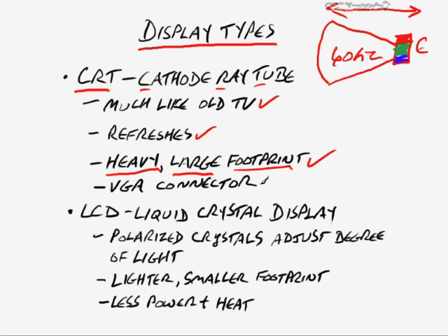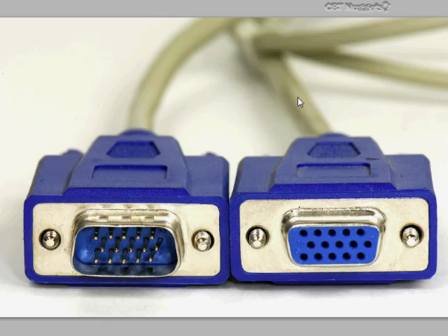And also, these typically use a VGA connector. And here's just a photograph of the VGA connectors, both the male side and the female side. Normally what you're going to be doing is you'll plug the female side into the monitor itself, and then the male side you'll plug into the back of the computer or the back of the video card, what have you. This is a 15-pin connector, which at least at first glance looks an awful lot like a standard serial cable because it's a smaller D shell, but it does use more pins, so keep that in mind.